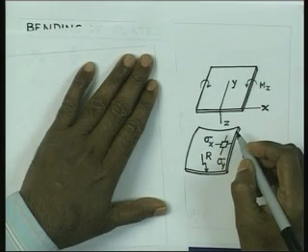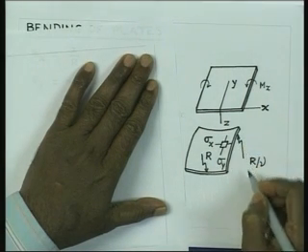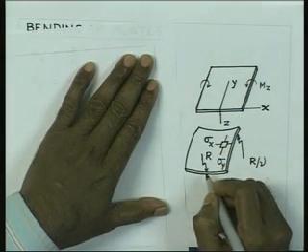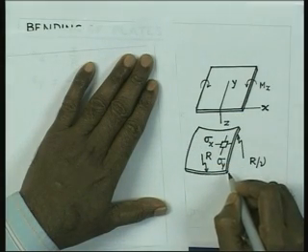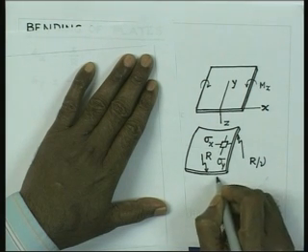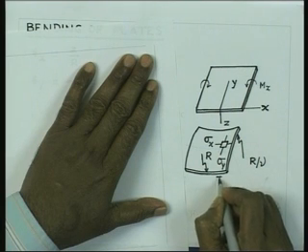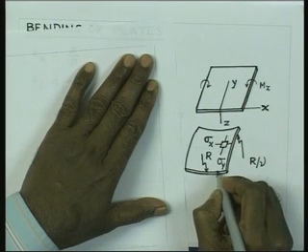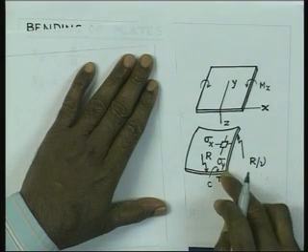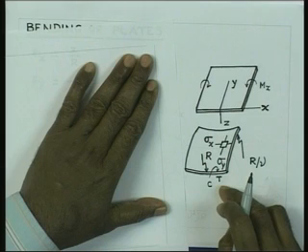and you find that because of that curvature, you are going to get some radius of curvature here in this direction. While you are having this curvature, you can appreciate that we will have tensile stresses at the bottom of the plate and compressive stresses at this top fiber. So, compressive at the top fiber and tensile stresses at the bottom fiber.